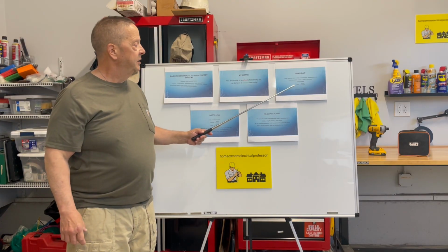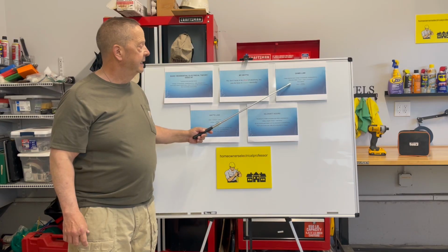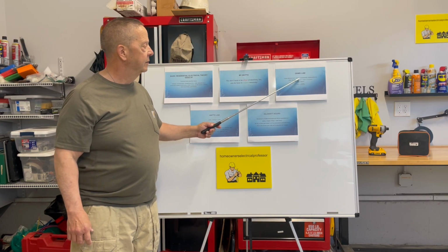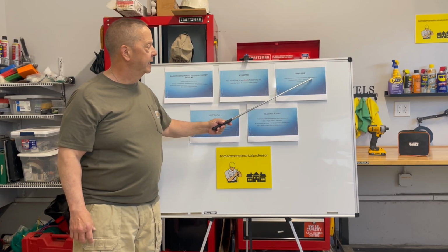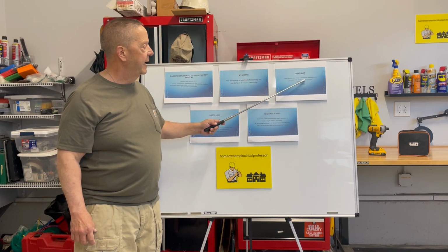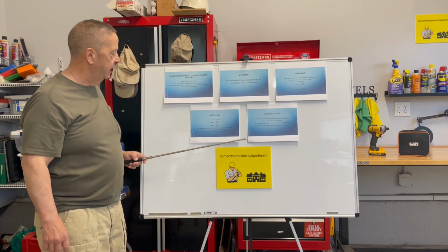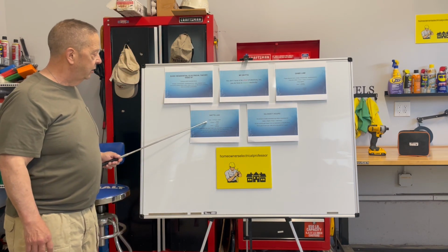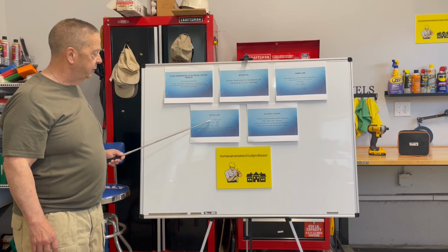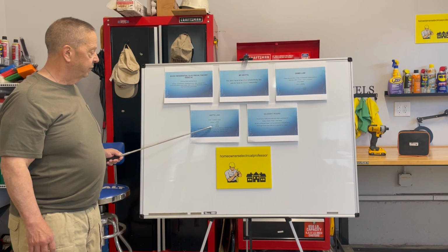The first basic law of electricity is called Ohm's law, and that dictates the relationship between the voltage, the current, and the resistance. Ohm's law states that voltage is equal to the amps times the resistance. You can use algebra to find out the other quantities. There's also Watt's law, which is voltage times amps, also a little bit of algebra. Sometimes watts is referred to as power.